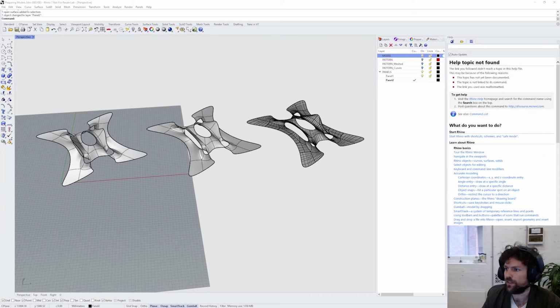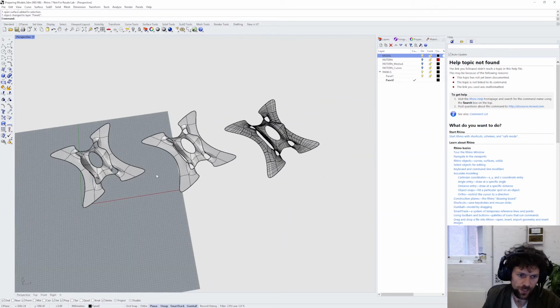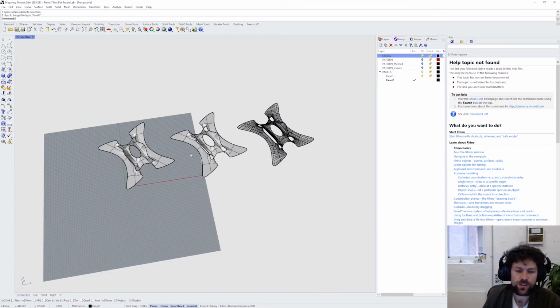The next thing to consider is where your model is located in physical space. So it's really important when you're creating mixed reality experiences to keep your model located at the origin where possible, just because this means that when the model is loaded up for the first time for the end user, it'll appear right in front of them rather than far off in the distance or at some unexpected location.